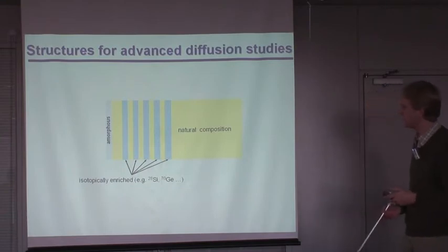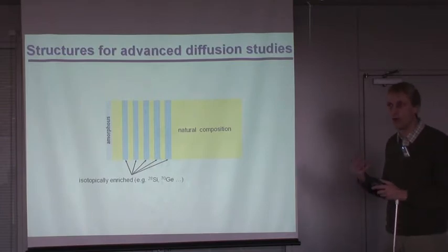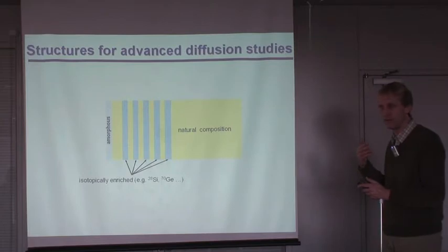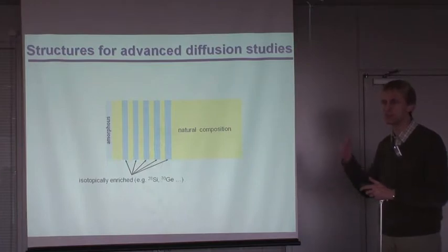And this we have done in the case of silicon first as an illustration of how powerful this technique is in order to determine the native defects and in particular the charge states of the native defects, because all vacancies and self-interstitials, they can exist in different charge states. They may be neutral, singly or doubly charged, positively or negatively.